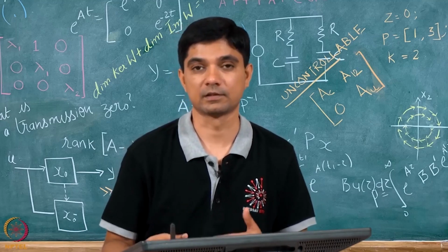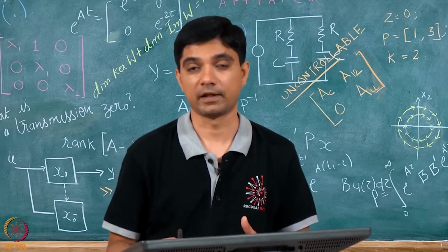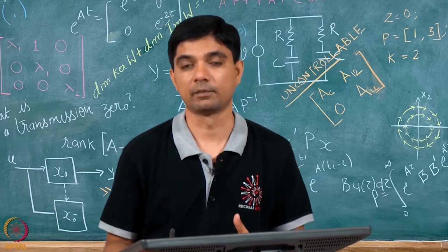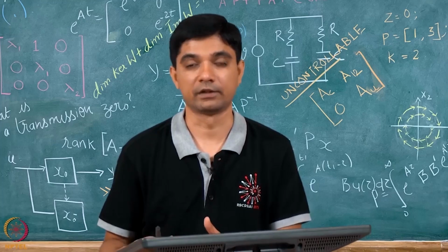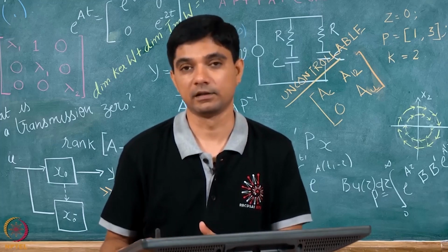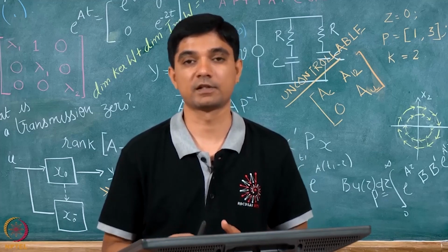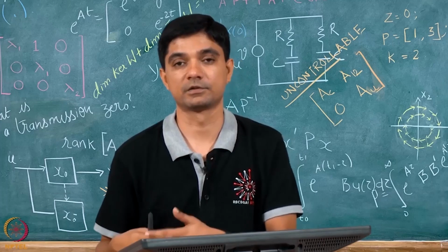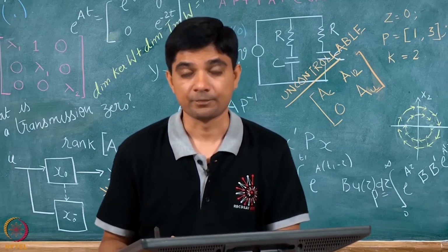So last lecture we had defined for ourselves a few concepts of stability, starting with just the notion of a stable system where the solutions were uniformly bounded. Then you had the notion of asymptotic stability, which did not tell me about the rate of convergence of my solution to the equilibrium point. And then we had the exponential stability notion, which had some information on how fast my solution approaches the origin. And of course, unstable systems, the systems which are not stable, are unstable systems.